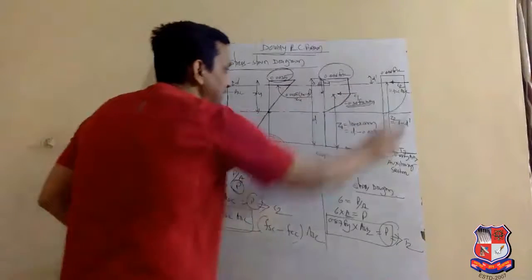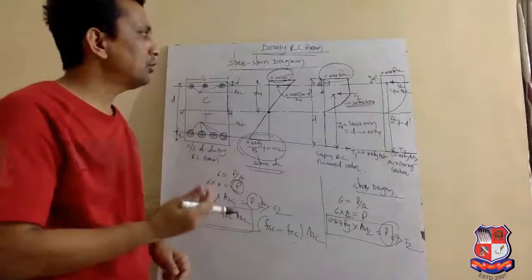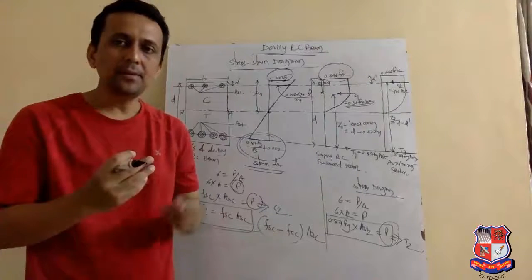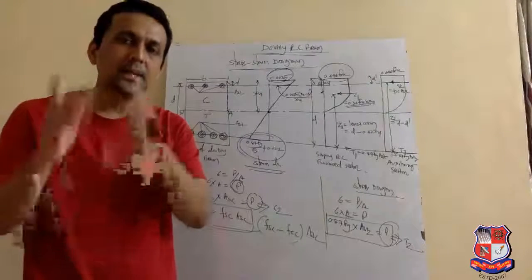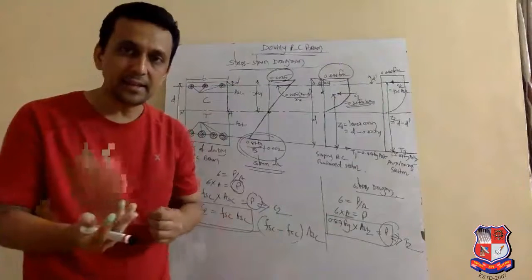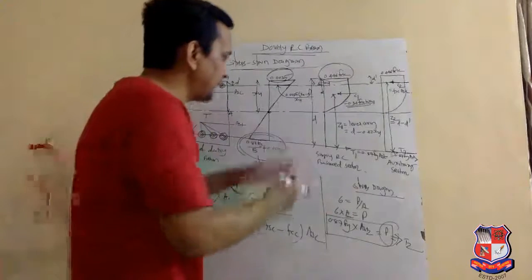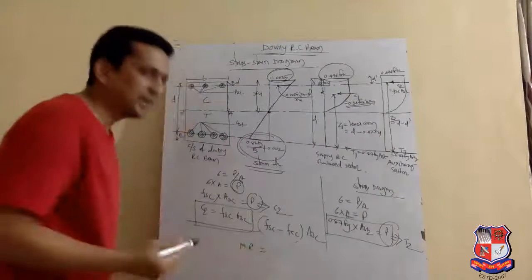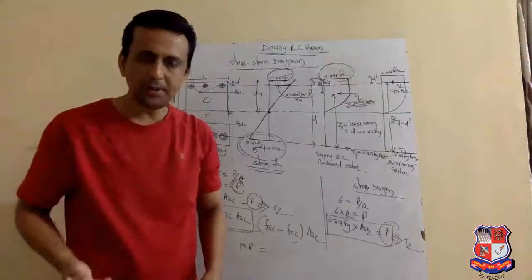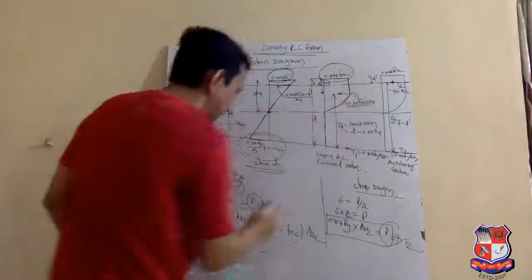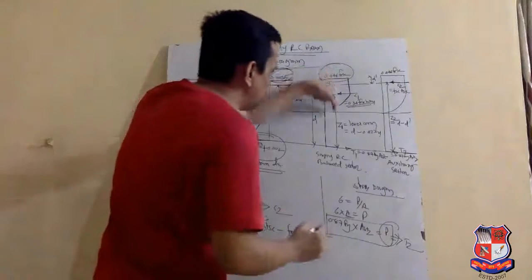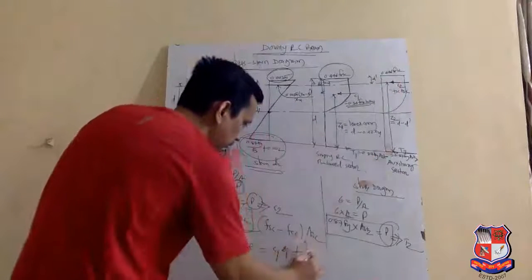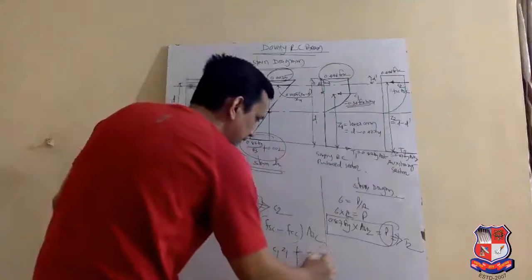From this stress diagram, if we want to find the moment of resistance of the doubly reinforced beam, meaning how much moment the doubly reinforced beam can carry, we can make the equation. Moment of resistance is force into perpendicular distance. So the force is C1, and its vertical distance is Z1, plus C2 and its vertical distance Z2.